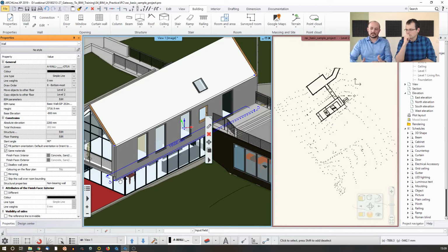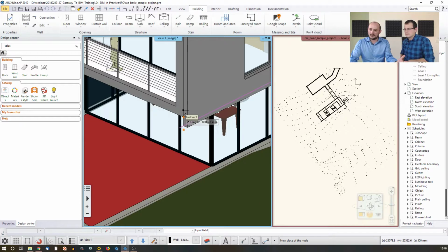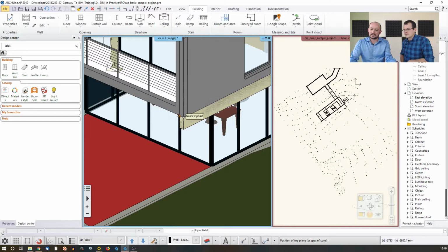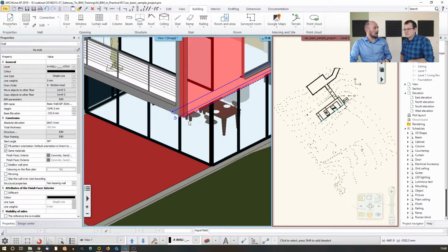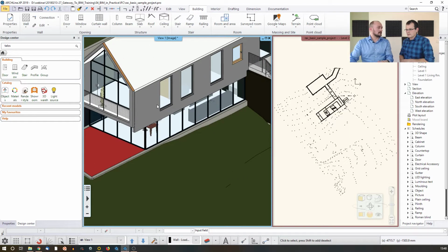So whatever was fixed with that, because you designed it in a very specific way, which that software can do, and this software has different solutions for that. So the software kept the 3D, but now I made it editable, and I can still go there and, for example, change the height. Well, that was the length. Yeah, sorry. So I just change the height and I just match it with the original one. So this is how I can edit it. The information is still not lost. The information is still there, but I can select what I'm willing to do with this wall, for example.